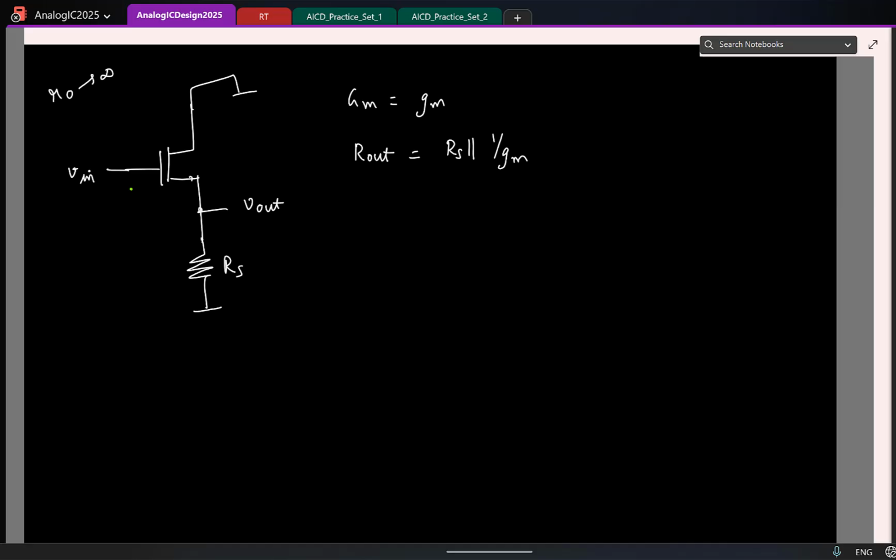I mean, that's why you prefer to do it this way, because otherwise you write KCL, draw small signal, write KCL and solve it. This is more intuitive, as long as you know what is the effective resistance looking into each node, and short circuit Gm is typically easy because you basically sort of short things.